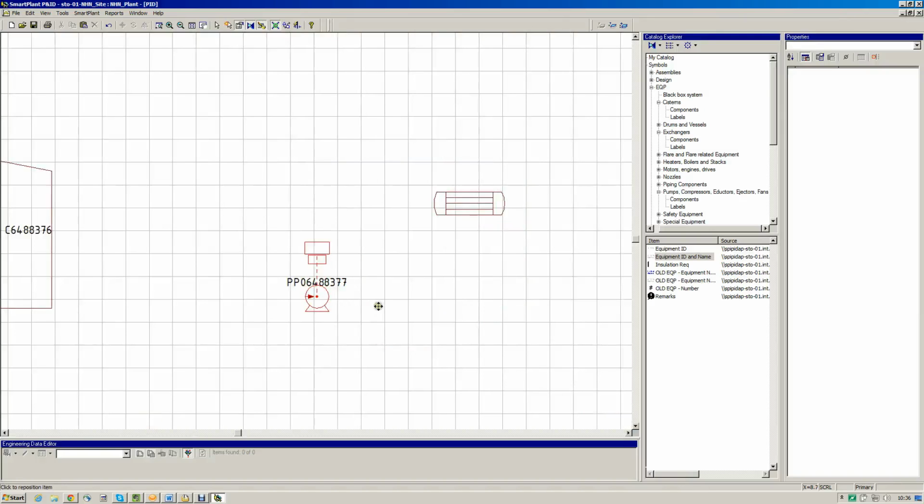I choose this equipment. Okay, I get that tag. And where would I like to have it? Underneath maybe. Okay. I still have the label tool. Heat exchanger. Okay. It ends up like here. As we can see on the label here, it has a name field and a tag field. The name field we can fill out here. We can call it whatever, like this, and it comes out here in text.